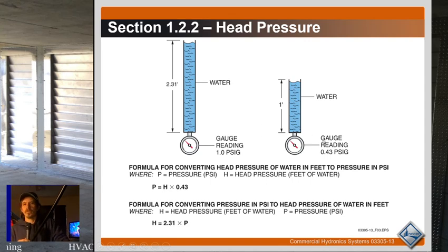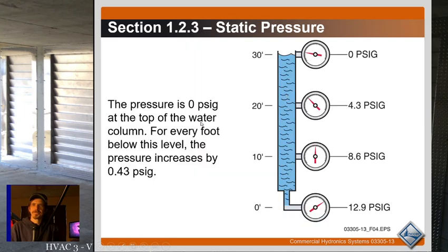It really confused me for a long time why we looked at feet of head on boilers. But if you learn about boilers, you'll figure out that the height in the feet of head that you lose is just another way of thinking about the pressure in the system. So think of those things as interchangeable. We just tend to use head pressure because it's an easier way to think about things once you get used to how you need to do it.